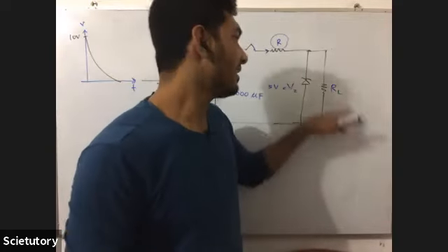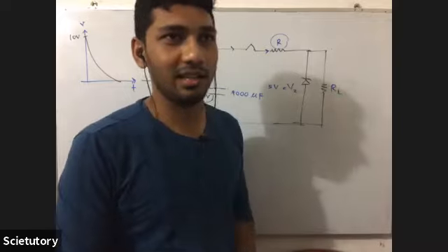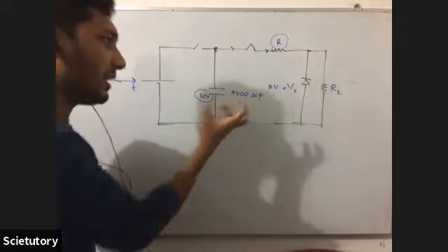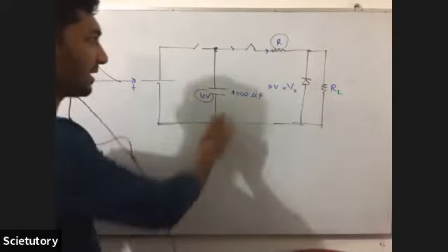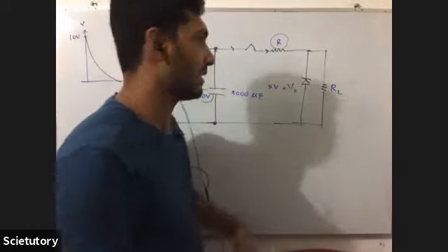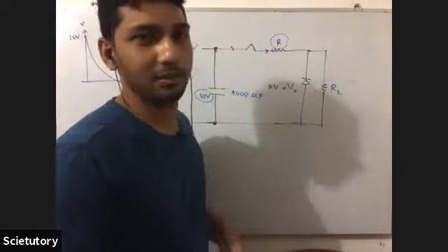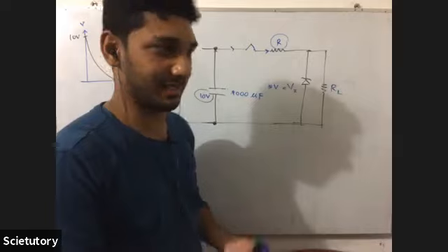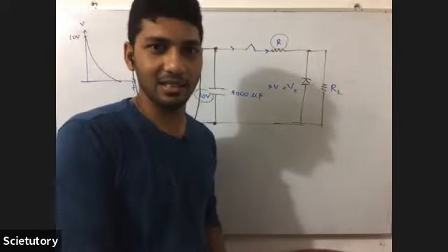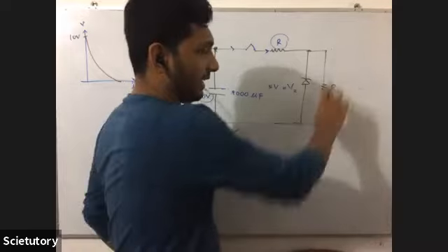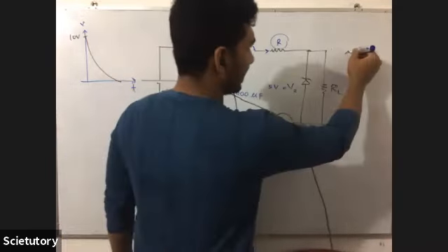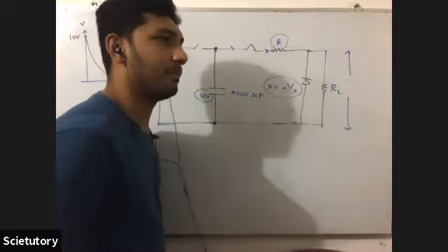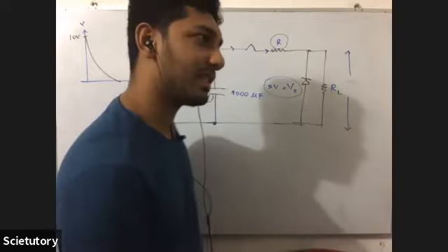It's very funny, no? They are telling us it's a suitable resistor. So they want us to think that this resistance can take some amount of voltage from the total voltage supplied to the circuit such that the diode breaks down. Did you understand that? It is a suitable resistor so that it gets sufficient voltage difference across it so that this Zener diode also breaks down. So we shall take it like that.